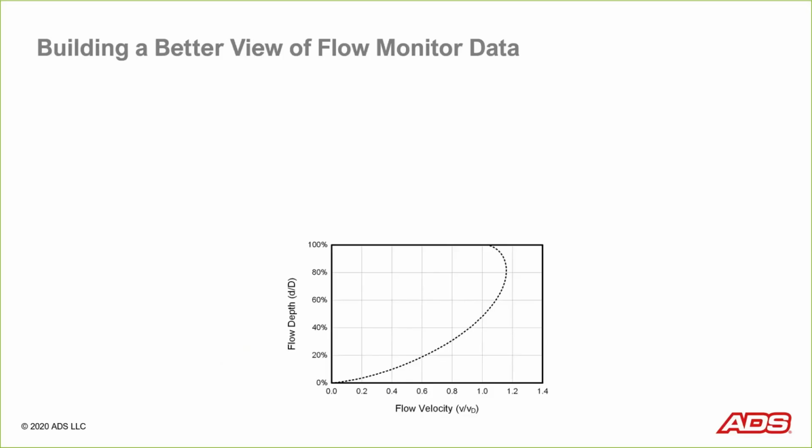Because most of you have seen this equation plotted just like this in one of your undergraduate engineering textbooks. You can pull almost any of them off the shelf today, flip through the index, and quickly find a graph like this. It's often referred to as a hydraulic elements curve. The only difference here is you have the depth represented as a percentage or a depth to diameter ratio, and you have the velocity represented as a percentage of the partially full velocity compared to the full pipe velocity.